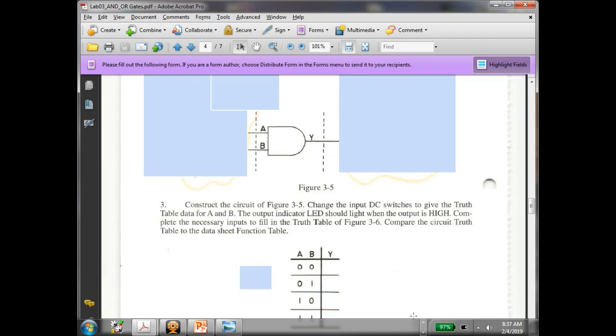So if I have an 8 input AND gate, it's going to take all highs to get a high. But I've got 255 other combinations that would give me a low. Understand what I'm saying? So which one of those would be normal? If I've got 256 combinations I could put on an input, which one would be normal? None of them. Now there might be a normal input inside a circuit, right? You understand what I'm saying?